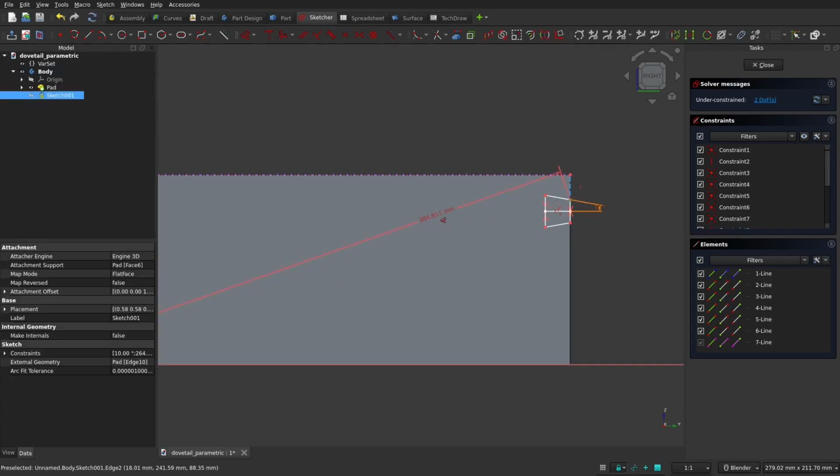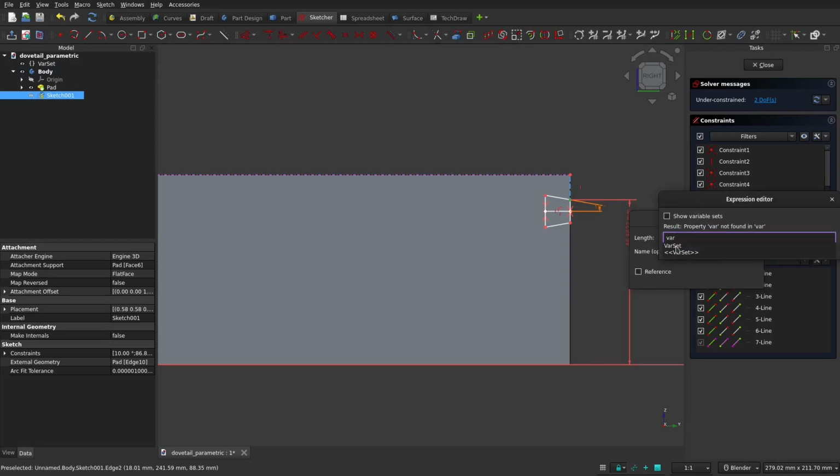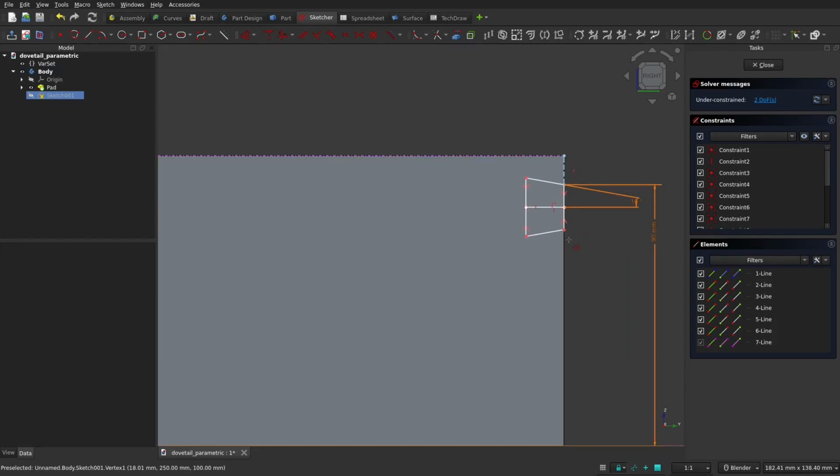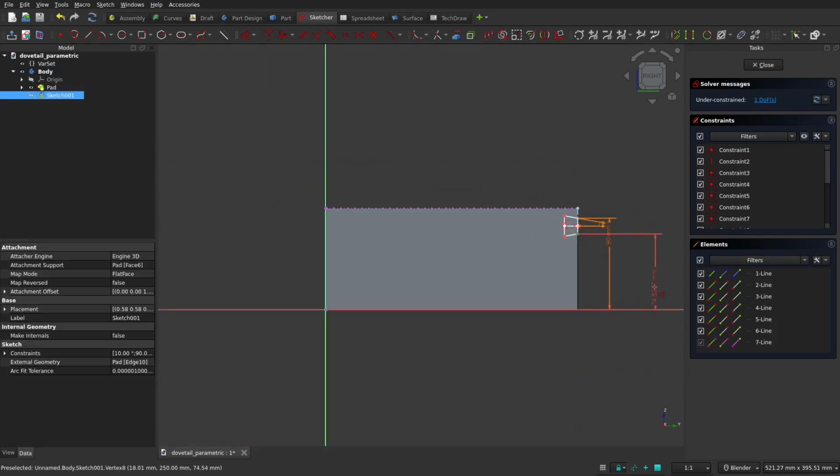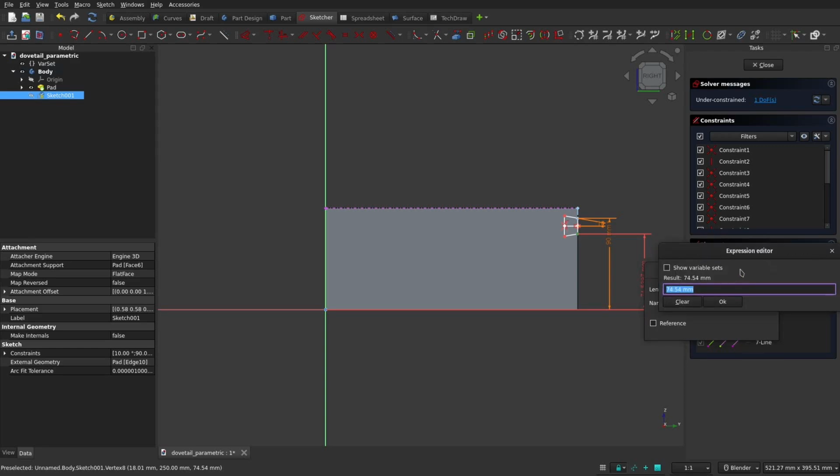We will now define the height of the offset from the origin. While this approach may seem unconventional, it prevents recalculation errors in FreeCAD. Therefore, we will input the value as the board_width variable minus the offset from the edge. We will define the socket size in the same manner, using the value of the board_width variable minus the offset from the edge, and minus the socket size. While this approach may seem non-standard, it prevents recalculation errors.